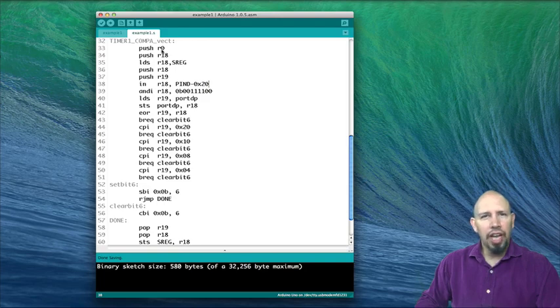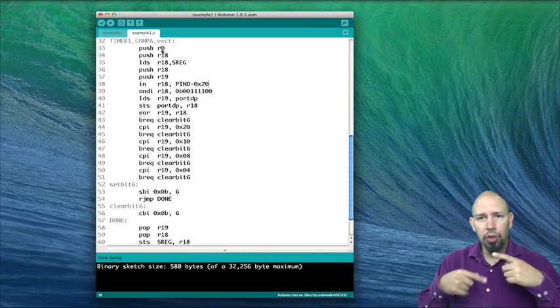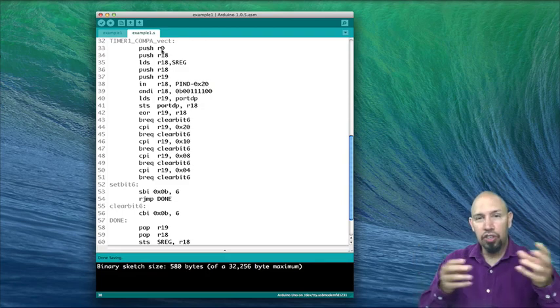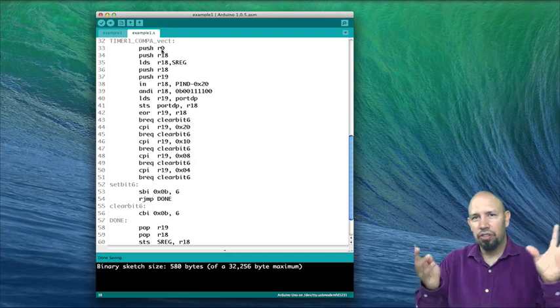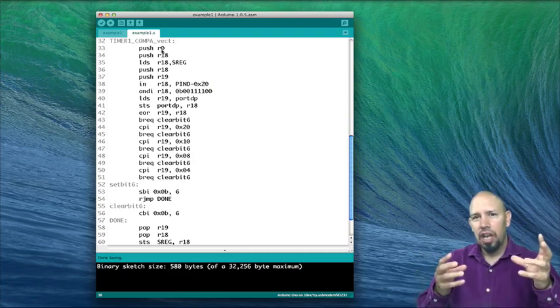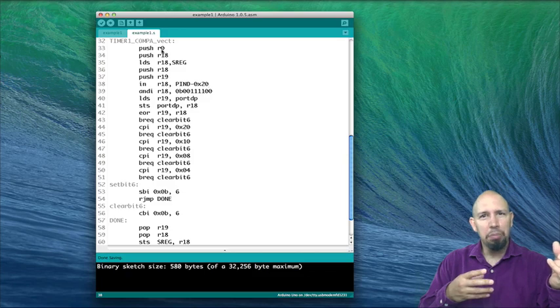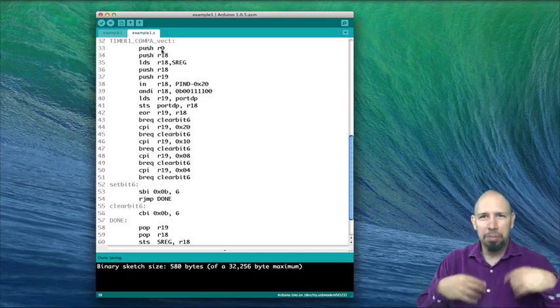Even though registers 18 and 19 can be left messy in a function, you can do that. In an interrupt service routine, you don't want to do that, because you could have some function in general that is using all the different registers, and it's in the middle of using a register when an interrupt occurs. So maybe it's in the middle of using register 19, and an interrupt occurs. When it comes back, register 19 is messed up. That messes up the program that was running.